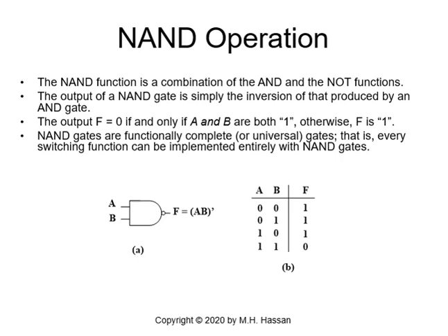So this is the NAND gate symbol, and the circle again signifies inversion or negation. The truth table will have A and B. 0 and 0 will be equal to 1, which is the complement of the AND gate. 0 and 1 is 1, 1 and 0 is 1, and 1 and 1 is 0.